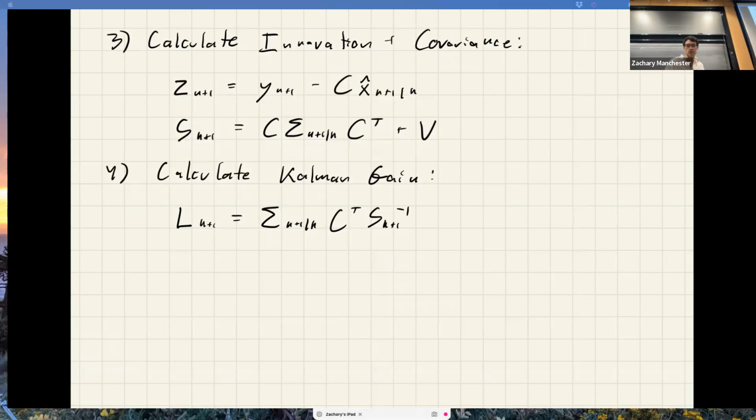One way to think about it, if you look at these equations: the measurement update is squashing your state covariance, which is what makes your covariance smaller. The prediction step is growing the covariance. If it's not observable, you're not getting enough measurements, or your measurements aren't spanning the full state space. So in some dimensions, the covariance from the prediction step is just growing due to process noise. There's an unstable mode. You can think about it that way if you like.